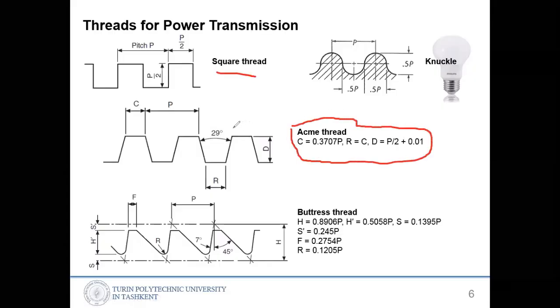So the parameters are like this. Different sizes, different shapes, and you can see different slopes. The size here is 7, but the other side is bigger, to hold the part more. When you transfer power, to prevent the threaded part from unscrewing, the angles are changed here. So more here is straight, but here is more sloped. We call this the buttress thread.